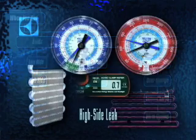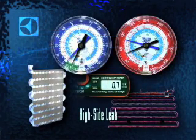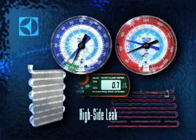High-side leaks will feature low readings on both the low side and high side, with a low electrical reading. The evaporator may be only partially frosted or not frosted at all. You should hear some hissing and gurgling at the inlet. And you should find the condenser slightly cooler than normal from lack of pressure. Also, the compressor will run very cool and quiet.